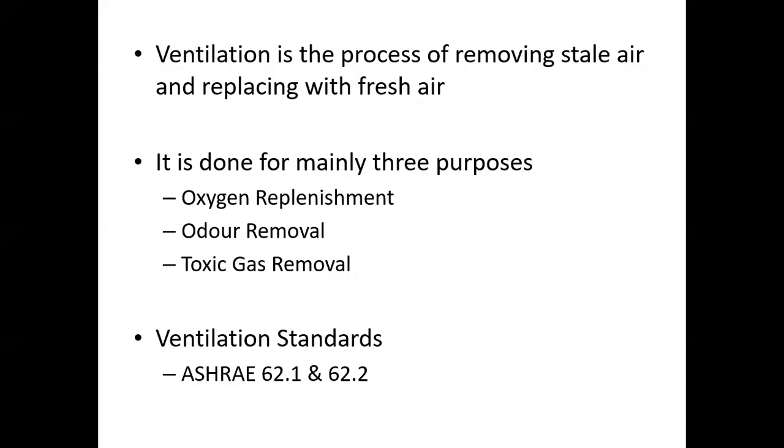The distances in between should probably be equal. You must make sure that each and every airflow is entering at the center portion, not in the corridors. You getting my point? It shouldn't be stacked up onto the corridors. So probably you need to maintain that according to the site aspect, according to the room space itself.